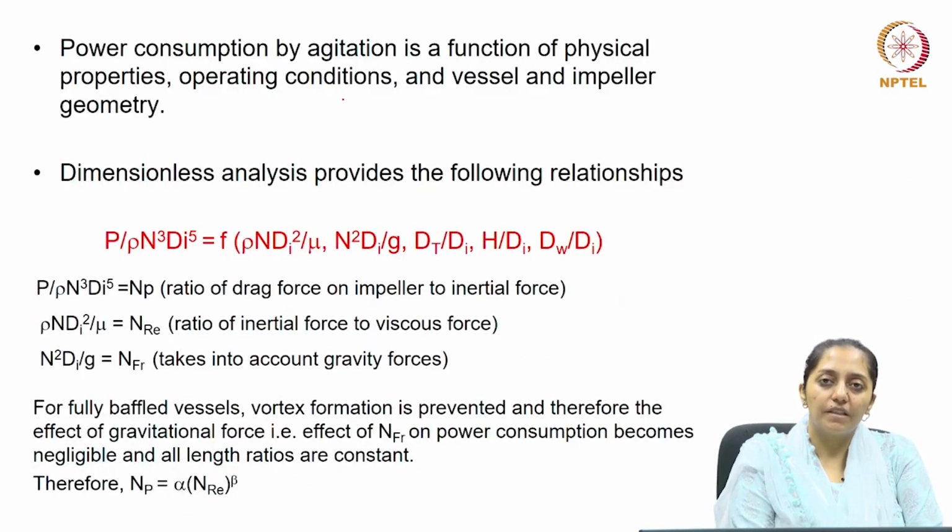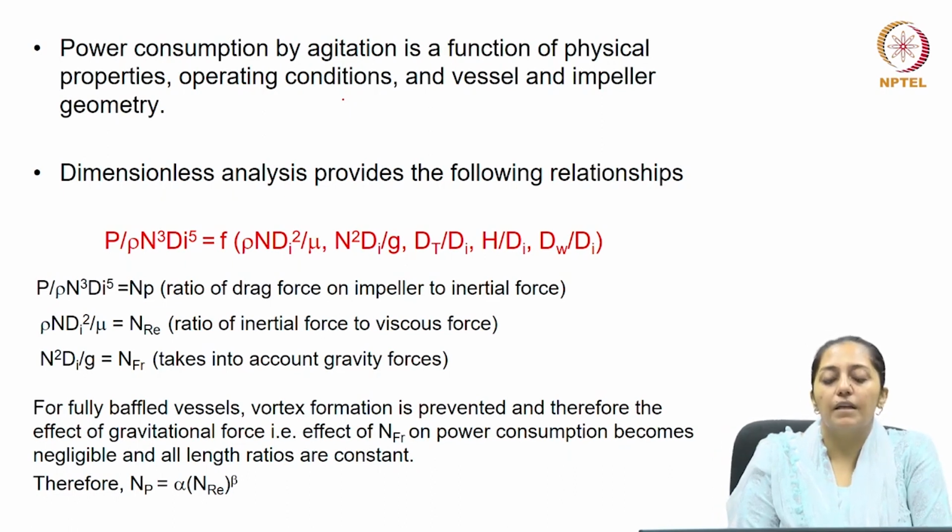Now, for adequate agitation, the power will be consumed by the impeller. So, how to determine the power consumption? This power consumption is found to be a function of various physical properties, operating conditions, and vessel and impeller geometry. So, again, dimensionless analysis is used to provide these relationships.